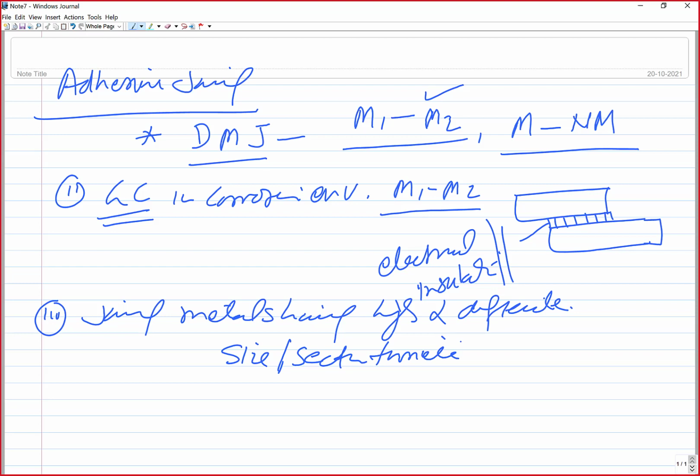Normally adhesive joining is performed on very thin wires, thin sheets, films, foils, etc. So developing a reasonably good joint of metals having a large difference in thermal expansion coefficient can certainly be done with great ease. Even metallurgical incompatibility between the two metals doesn't come in as a barrier. Then next is the bonding of multiple thin sheets, which can be done very easily and effectively.